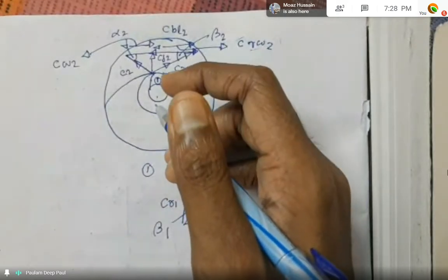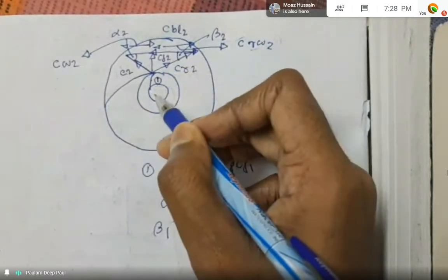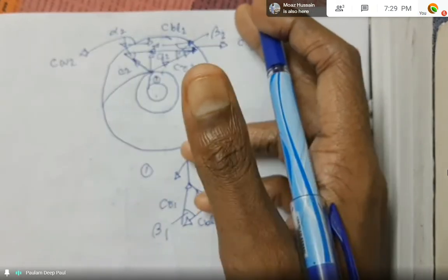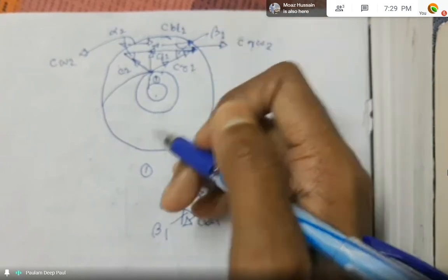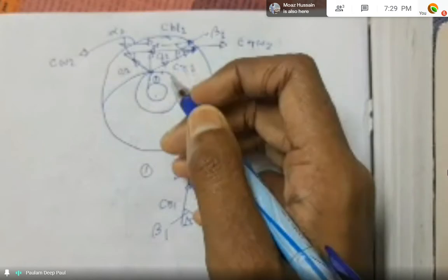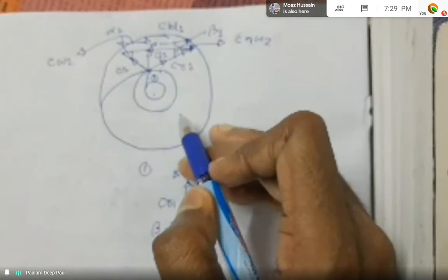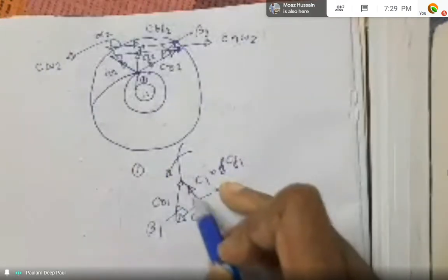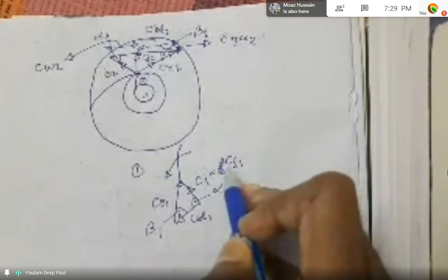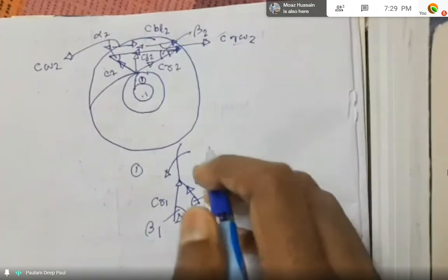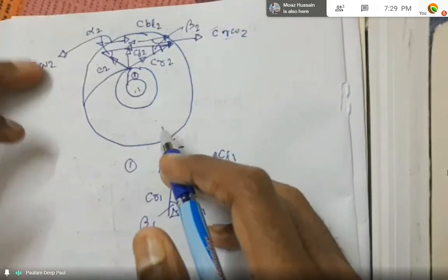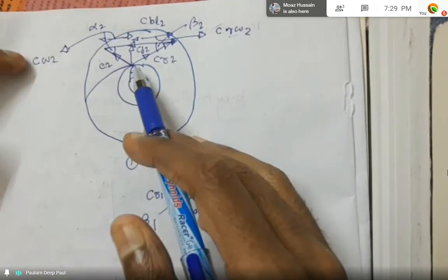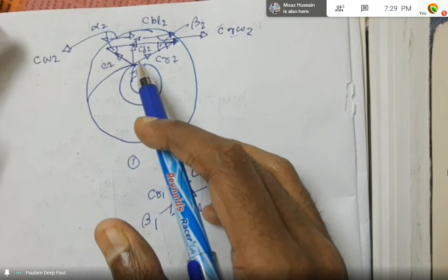Now, how it works is, air enters the eye of the impeller, that is this, at a mean radius, say rm, with a low velocity, C1, at the atmospheric pressure, that is P1. Now, depending upon the centrifugal action of the impeller, the air moves radially outwards. So the air is moving in this way, in the radial direction, as I already stated, because you don't get a whirl component here, and the flow velocity is equal to the absolute velocity. And during its movement it is guided by the impeller vanes, that is the inlet vanes, you can say, impeller vanes.